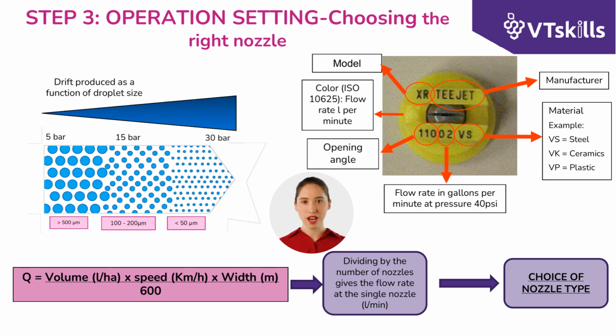Full or hollow cone nozzles generate fine droplets and improve penetration, ideal for dense canopies and hidden targets. Fan nozzles, standard or anti-drift: uniform lateral distribution, useful for less dense vertical panels or targeted treatments. Air injection nozzles reduce drift due to larger droplets and internal air bubbles, limiting fragmentation into ultra-fine droplets. Each nozzle has an ideal pressure range that influences its performance. For example, anti-drift nozzles operate at 3 to 8 bars.